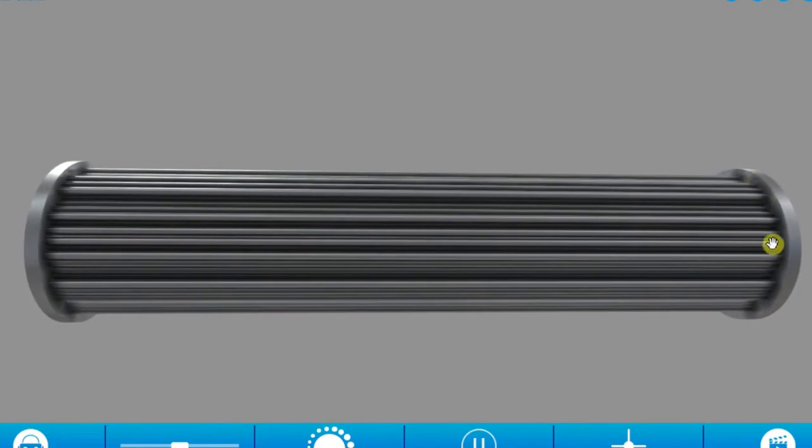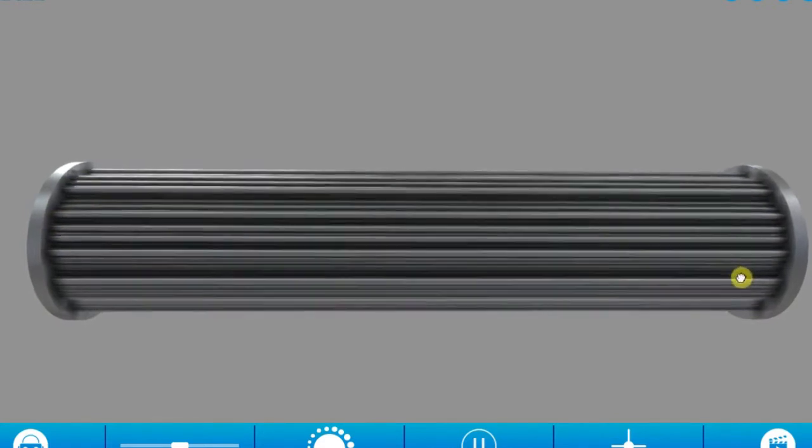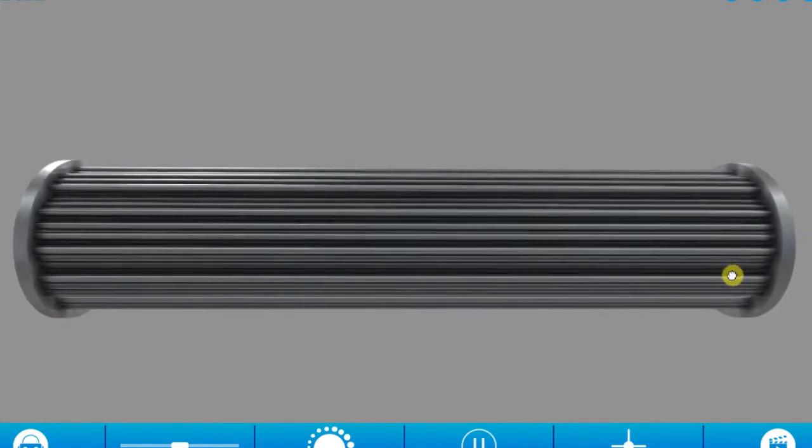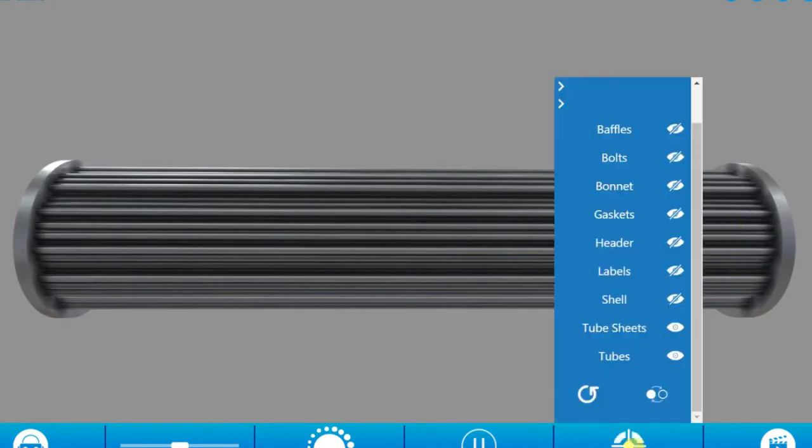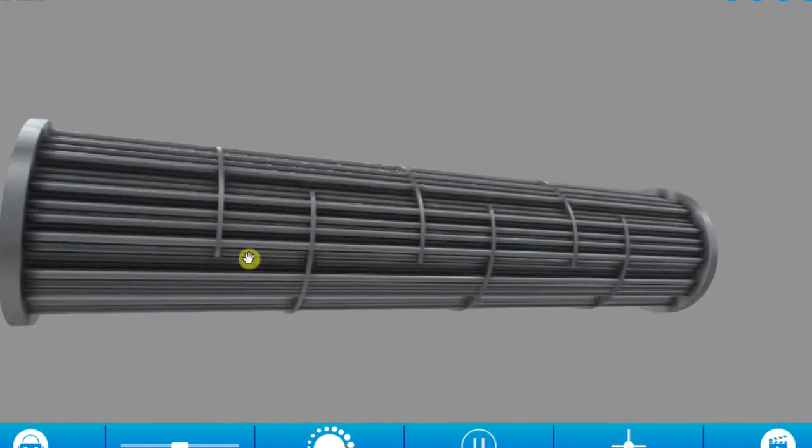So here's one tube sheet, sometimes known as the rear tube sheet. Here's the front tube sheet, and the shell side fluid is going to remain in this space. So that's the pressure boundary for the shell side fluid. We want to fix the tubes in position using more than just 2 anchor points. So we'll use baffles as well. And the baffles just add some extra support to help keep the tubes in alignment.